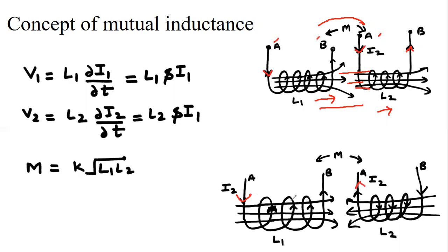In this, in the first coil, current is entering from terminal A, while in the second coil current is leaving from terminal A. So here the fluxes are opposing each other. Now, what are the equations related to the inductance? The voltage V1 is linked with L1 di/dt. First, this is not V1, this is V1(t), because voltage is a function of time. For simplicity, we are not showing the (t), and this is I1(t). So first, V1 equal to L1 dI1 by dt.